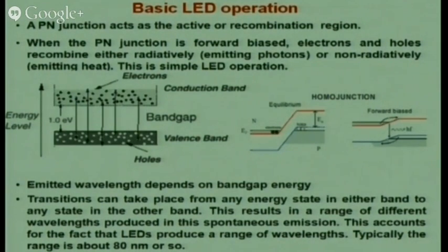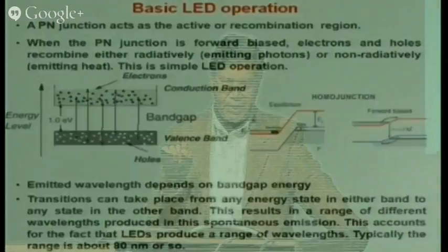What we need in communication systems is a single mode output, right? A single wavelength output, because dispersion effects take place, because each wavelength will travel with its own velocity, right? So if I send a pulse and that pulse carries a number of wavelengths, it spreads out at the detector end, right? So what we need is a source that produces a single, monochromatic wavelength, a large output, right? But while considering the options, what is available to us, what we can do further.